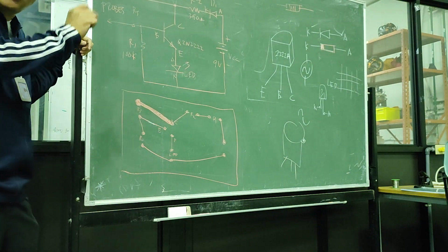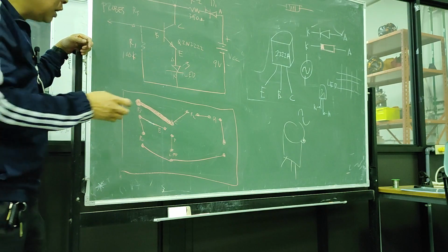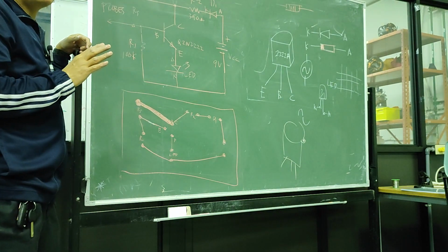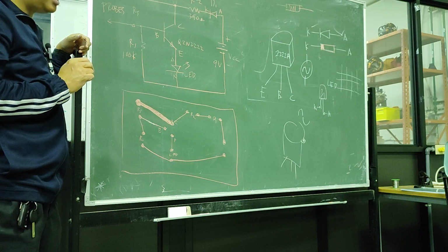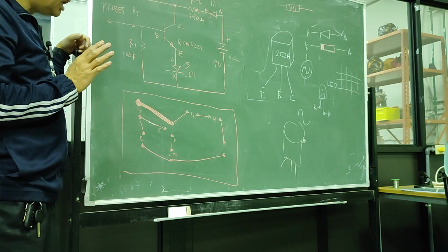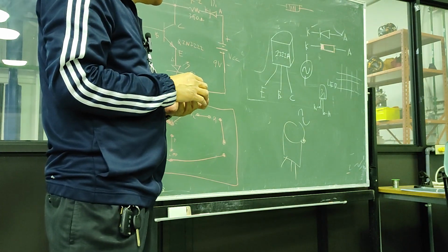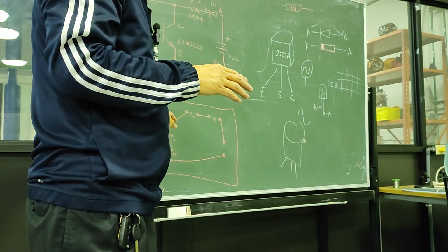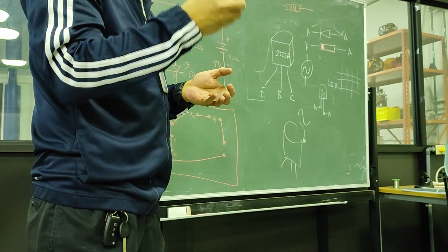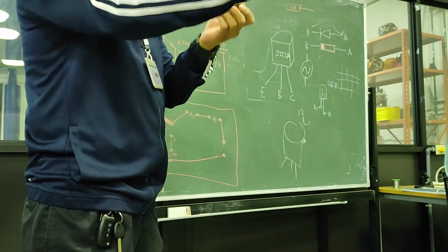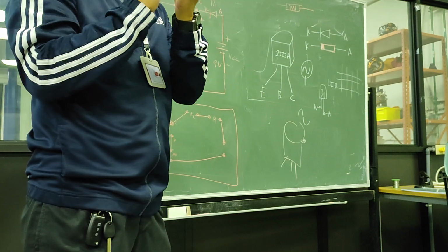Right? Simple. Like drawing. You are following only the connection. You got it? Okay? So now that completes the layout of this simple circuit. Okay, so it's simple. Now, the next thing you need to know is, after you design it, you will drill every pad. Then I will give you components, and you have to solder the components on the board.